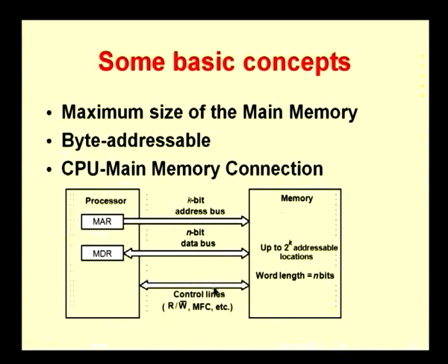And then we will have control lines, a read write control line, and maybe you may also have a control line which comes back as feedback from the memory when an operation is completed. So, this is typically what you will have in terms of the interface between a processor and a memory. When we talk of any memory device, we need to understand how the addresses will be specified, how the data at that particular address will be obtained, and what the control lines are that need to be specified for that. When we talk of memory again, there are certain terms that we normally refer to.